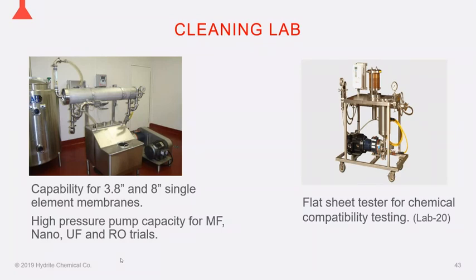But another thing that we can do is sort of the large-scale version of that practical soil test, which is putting the membrane in our test unit and running a couple of washes on it. And this is usually a secondary step after we think that we have an idea of what the foulant is, but it's a follow-on that we utilize to sort of verify that this is the wash that's going to solve the problem on the major system by scaling it up.